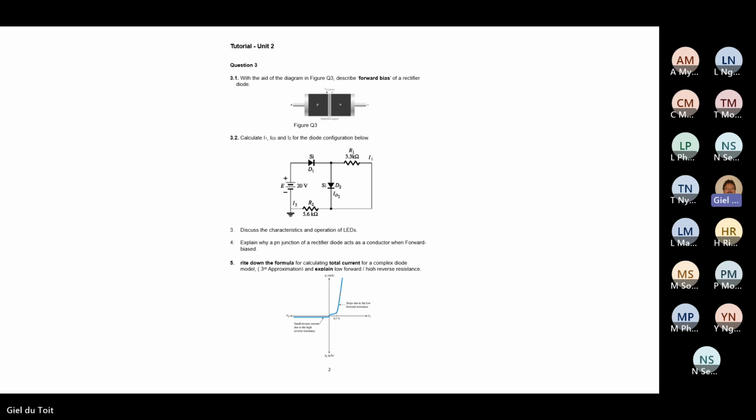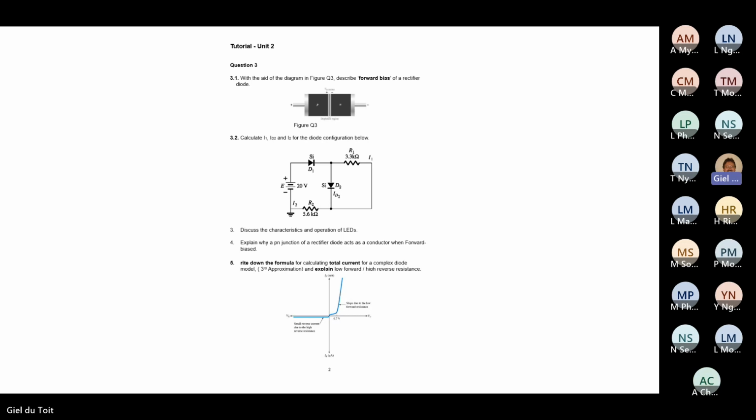Okay, so they are also asking what is the current through ID2. We know this is 0.7 volt over D2. What am I saying? 0.7 over D2. And we know there's 0.7 over D1. So the total volt drop will be 1.4 volt. So calculate the current there.